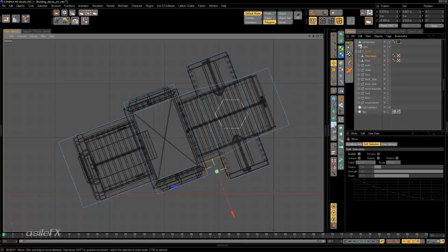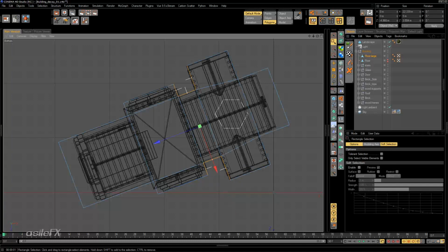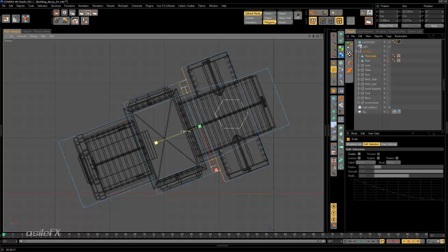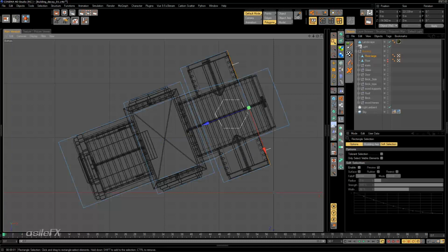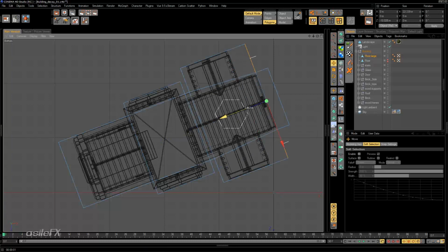And what you can do is switch to the move tool, right click, and just make sure that you have the right option selected. So take a look, down here we have axis, and then we can change the world, the object, root. So just making sure that axis or object is selected. What we can do is add, holding down Shift and adding those other polygons, and just squish those together, or close together. And then take those polygons on the end, move them back.